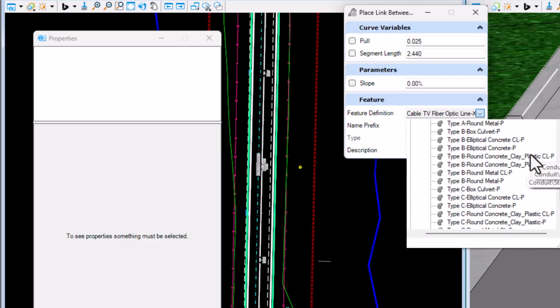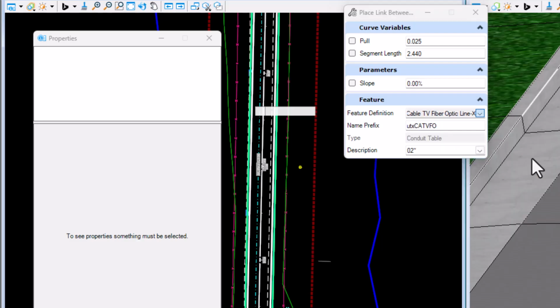So centerline display in plan view will just display one line down the middle, whereas the other one will show the extents of that pipe, so two lines along the diameter, the inside edge of the pipe. So it's just 2 different ways to display.